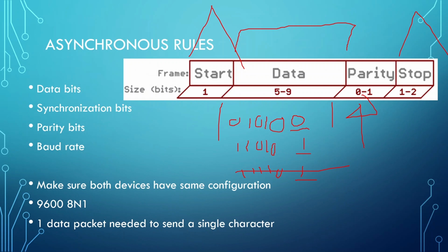We've already talked about baud rate. Yeah. So, the biggest important thing here when it comes down to serial communication, in my opinion, is making sure everything is set up the same. Device A's settings are the same as device B's settings. As long as that's the case, you should have pretty small or non-existent errors in getting those devices to communicate.